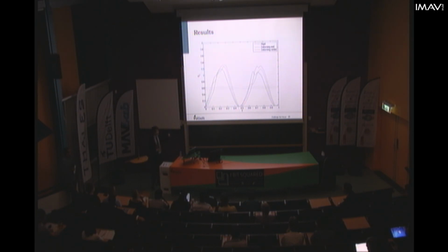Also, I did single wing simulations, simulating, for example, 10 cycles, and because this is hover, the wake of all the vortices of course builds up, and you can see that once in a while suddenly the wing interacts with the wake, so it might never become fully periodic simply because it's hover. Does that answer your question? Yes. Okay, great, thank you.